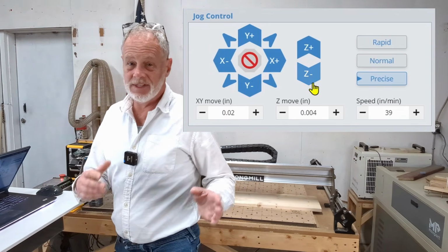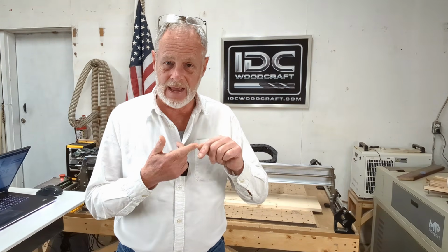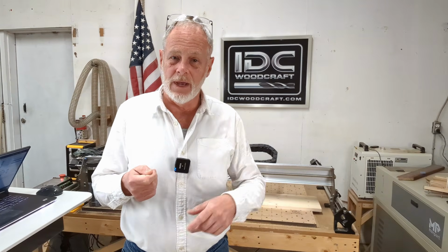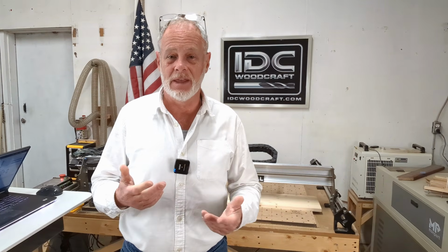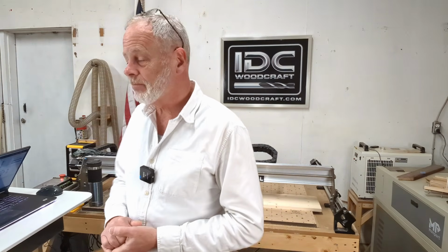Now, how do you set the Z value? Well, there's 2 ways you can do it. Number one is you can eyeball it. You can nurse the Z down with your router bit in it until it just touches the project material. I like to put a little piece of paper under it and wiggle it around until the piece of paper stops. Then we can set our 0. The other way you can do that is by using the probe, which I'll get to in just a moment.